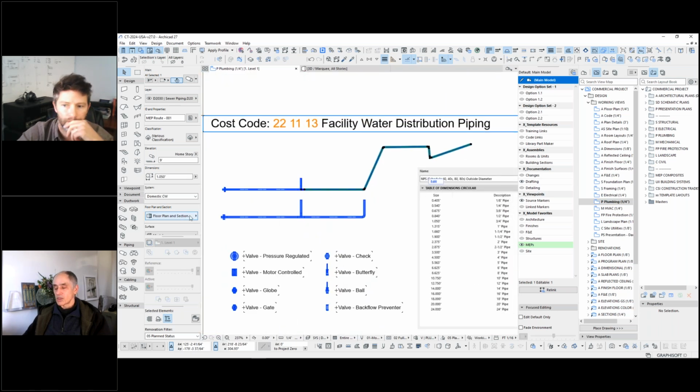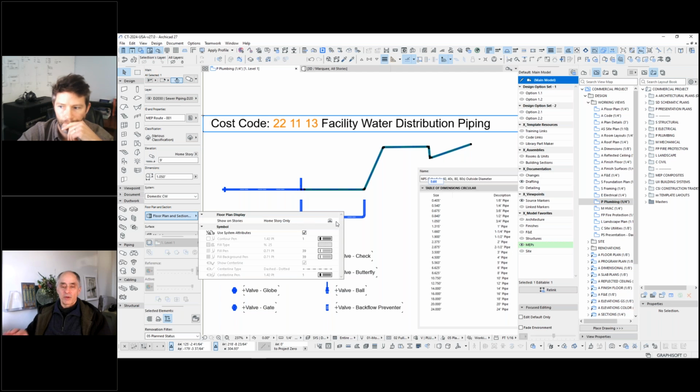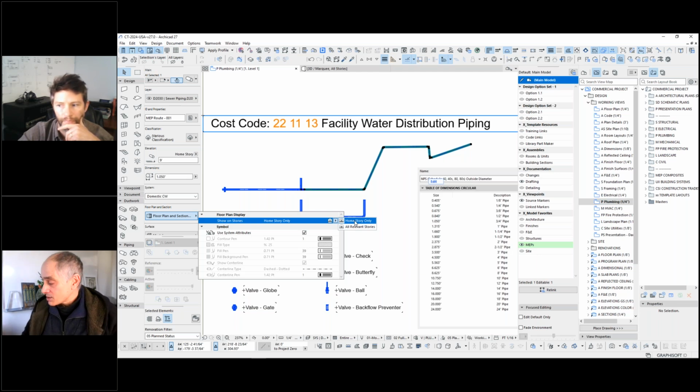But those view controls, like he was talking about, saying it's either on one story or on relevant stories, and relevant by definition doesn't include the story above. Now I do have a workaround for that. Here I think it will work because I actually tested it on something similar conceptually. You say this pipe, which is underground, shows on all relevant stories.